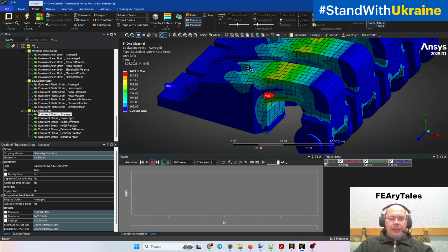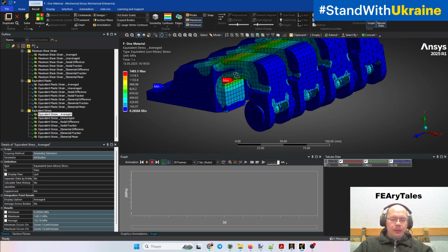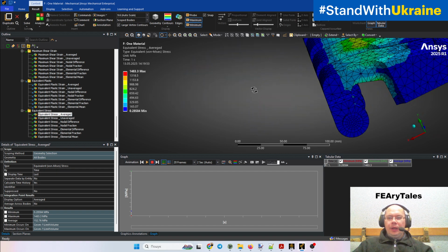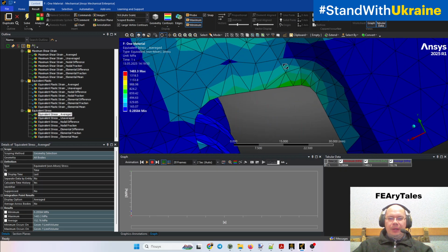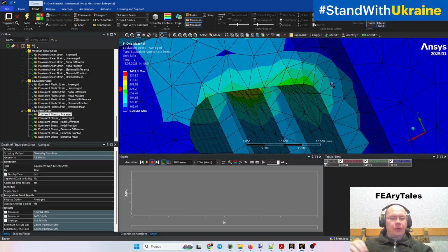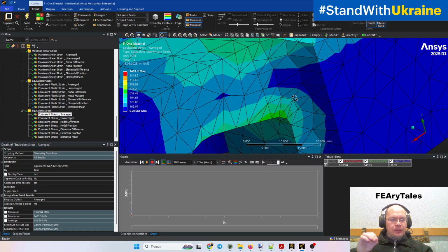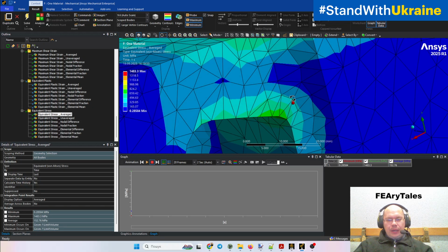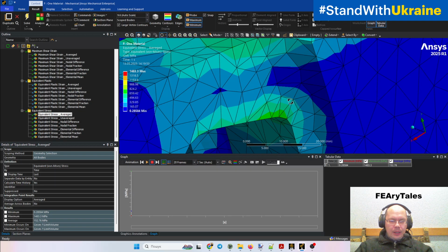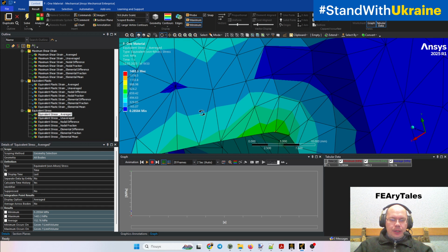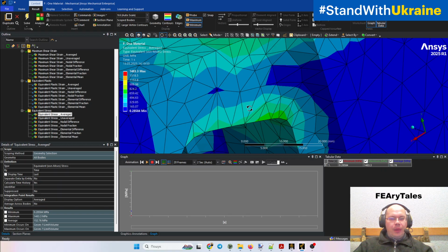We have this line here on the best mesh, the hex mesh with the second order element, and we have the same picture, the same behavior on the worse, coarser mesh with the linear tetra element. We already have a video about comparison of different types of meshes. You can find it here with the link, which I add. And in general, we can see that it's one line, the same as the first.